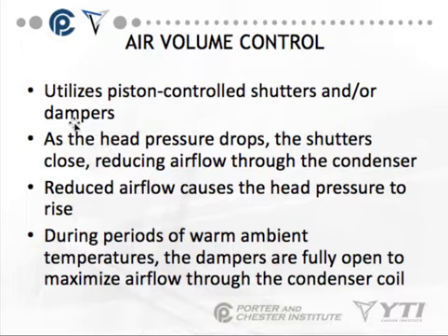Remember, as we talk about any of these controls, as we reduce airflow, less heat is rejected from the condenser, and therefore the pressures will always rise. The reason we want to do this is because we want to maintain our evaporator pressures. We do not want our evaporator pressures to drop too low, where the evaporator freezes up at a low temperature, or can just not open our TXVs and everything else, or our EPR valves may not open all the way. So we want to maintain the design pressures as much as we possibly can.